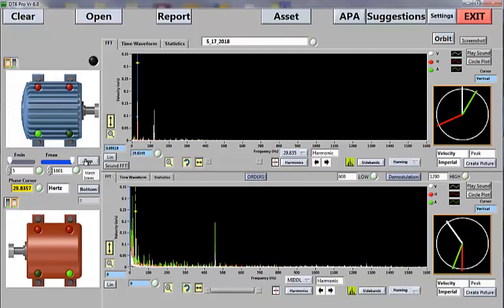I'll go ahead and scale it to the top, so that we can look at the driven end compared to the drive. And the first thing we'll notice is the driven end seems to have much larger vibration and be noisier than the drive end, especially when we go between these two. And even if we look between these two, the outboard on the driven end seems to have much larger vibration compared to its inboard end.